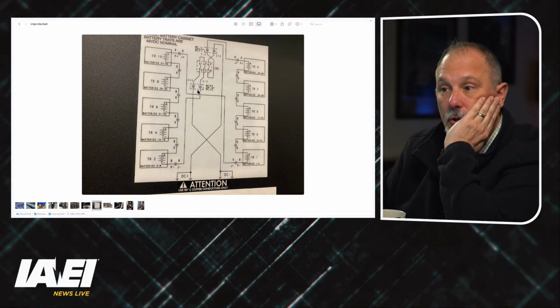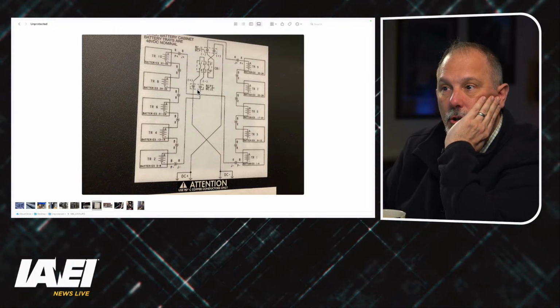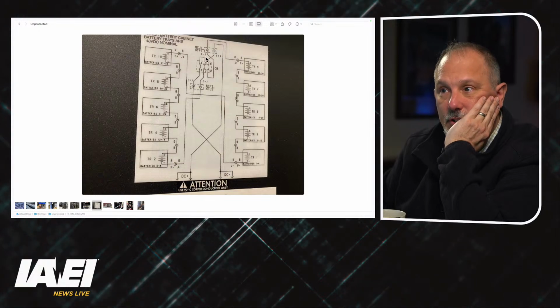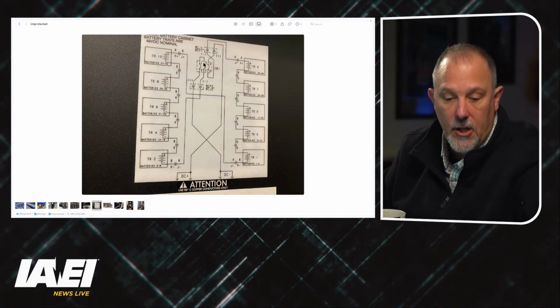But I do have a circuit breaker. So coming out of this enclosure, I have protection for the external conductors, but in the enclosure, I've contained all those conductors in a listed assembly and providing protection through other means that are governed by the UL standards, right?